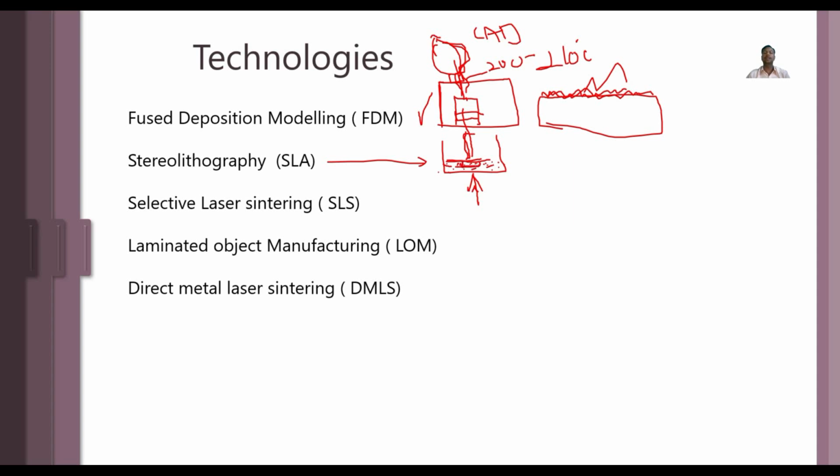Since it is preheated, the material sticks properly to this surface. As soon as the material is built, the part will go up. So this is anti-gravitational object printing that we can see here. Whereas in the other process, the object is printed on the surface and built layer by layer from bottom to top.